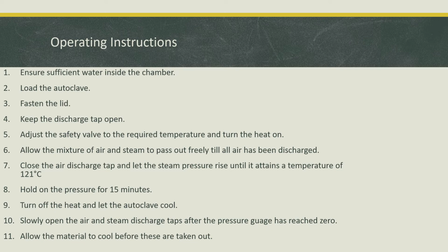Hold on the pressure for 15 minutes. Turn off the heat and let the autoclave cool. Slowly open the air and steam discharge taps after the pressure gauge has reached 0 point. Allow the material to cool before these are taken out.